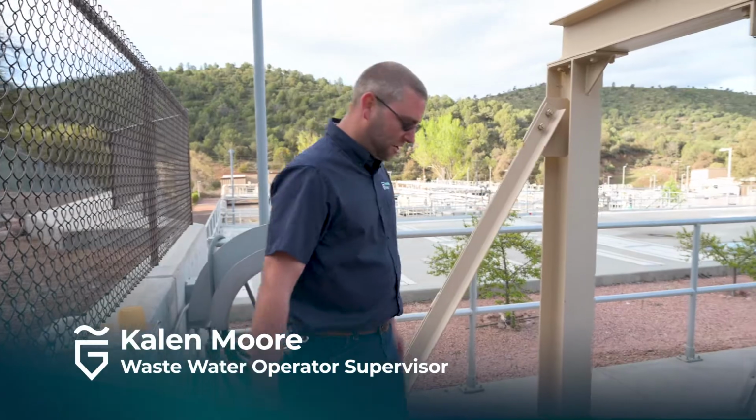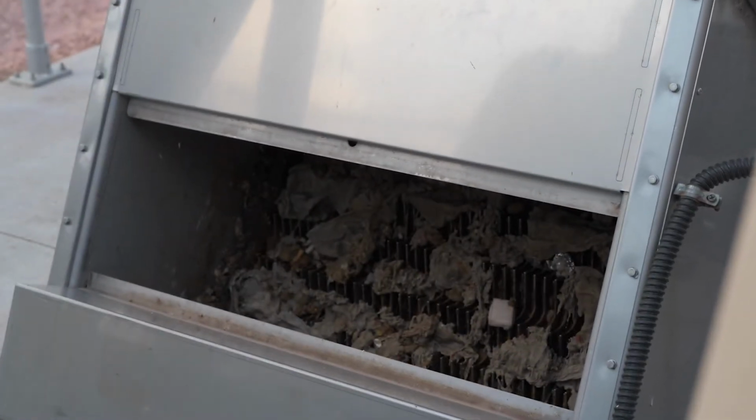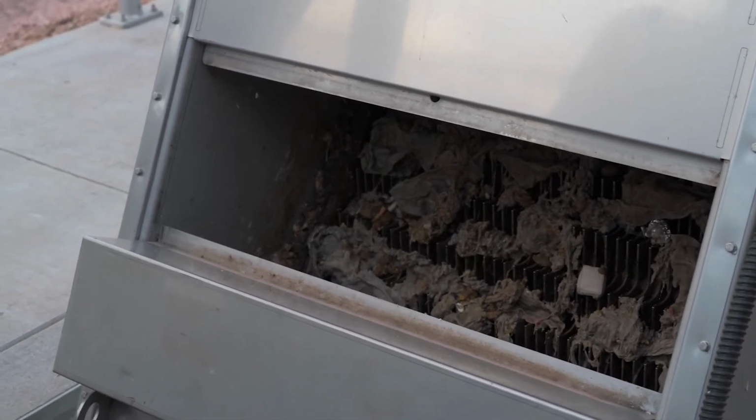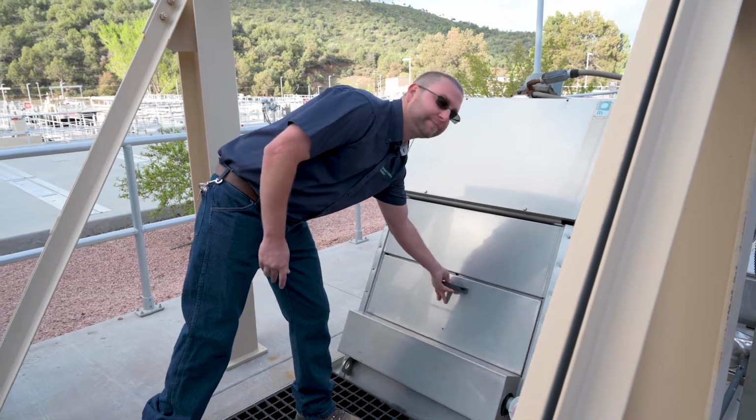This is the beginning of the treatment process at Green Valley Water. Here our influent flow comes into our step screen to help remove all of our rags and unflushables. We have to remove them to protect the rest of the plant's equipment.